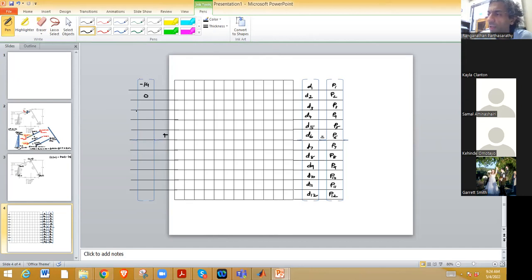Then you have 20 kip-feet counterclockwise. Let's convert to kip-inch, so 240. Counterclockwise, so positive 240, right? Then second joint, you have 13.33 going clockwise for this vertical member, and for the inclined member you have 112.5 going counterclockwise.